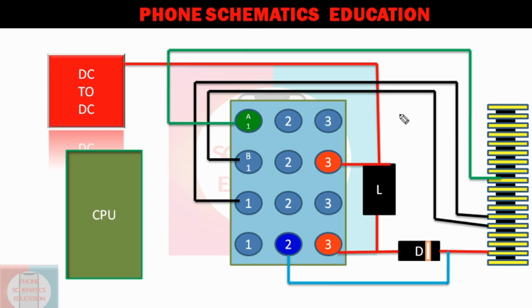Use a test pin, right? Red probe on a ground. Okay, got that. Now first black probe here on this point, anode line, red probe on a ground. If you get, suppose there is a value around 500, that means this line is connected to the IC. Now turn the probes, red probe on this point and black probe on a ground.